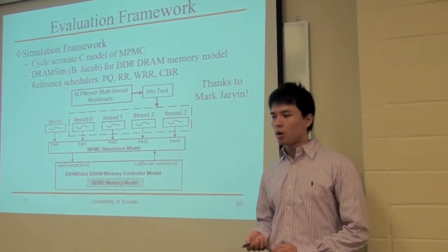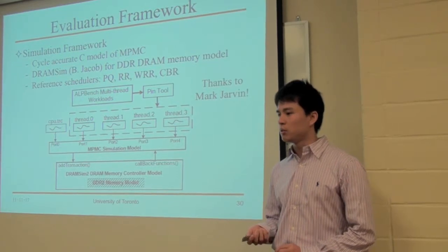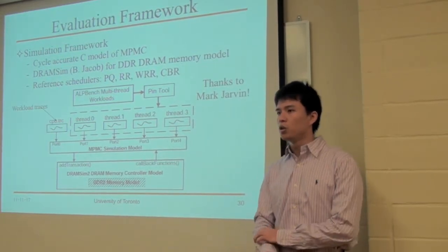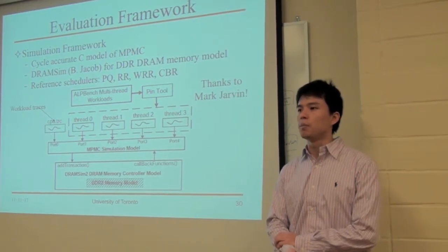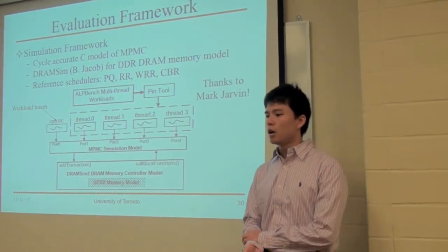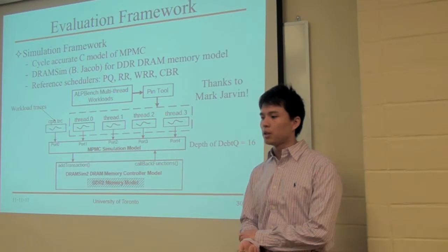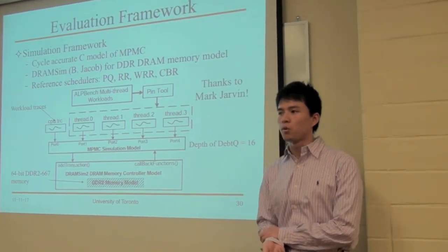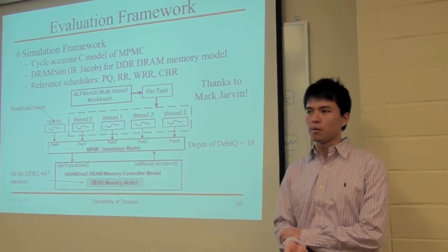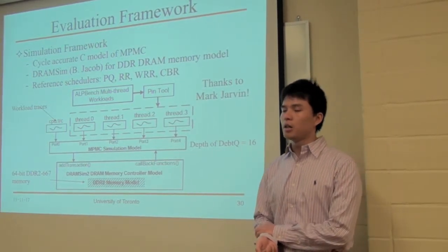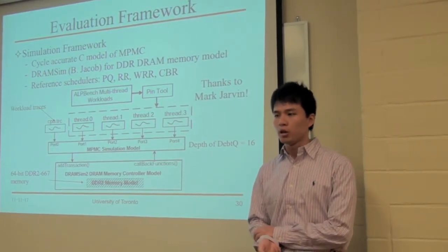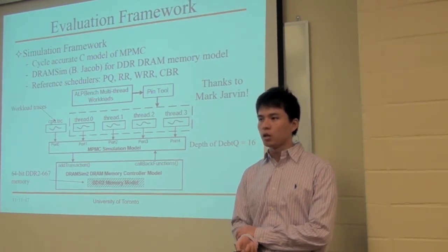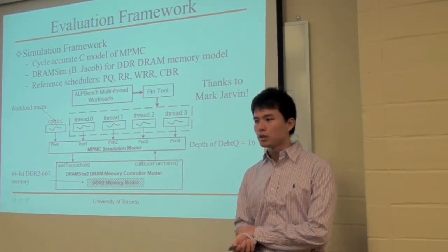We drive our multiport memory controller C model with different types of workloads, including CPU cache workload and multimedia workloads. We set the depth of the queue to 16. We test using a 64-bit DDR2 memory. Finally, we compare our test results with priority queuing, round robin, weighted round robin, and CreditBorrowRepay schedulers.